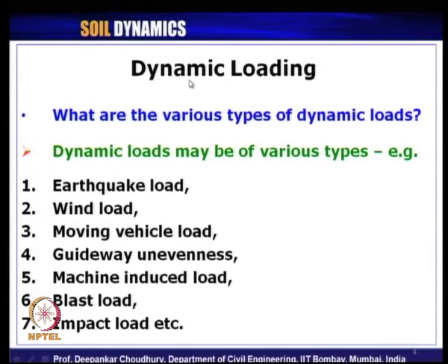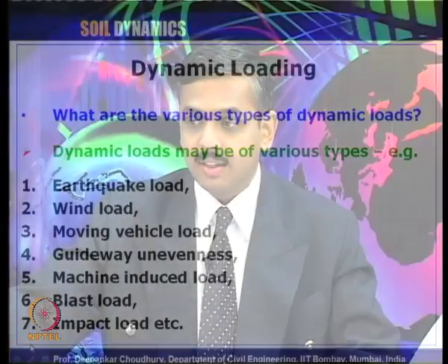The dynamic load must vary with time, and we have seen examples of various types of dynamic loads like earthquake load, wind load, moving vehicle load, guideway unevenness, machinery induced load, blast load, impact load, etc. But that does not mean all time dependent loads are dynamic. There can be live load also, which is not dynamic in nature.